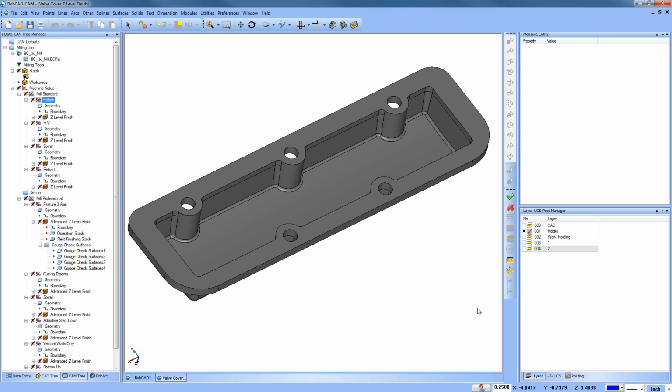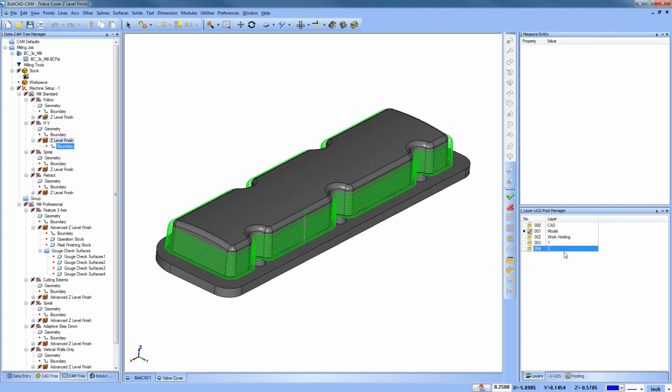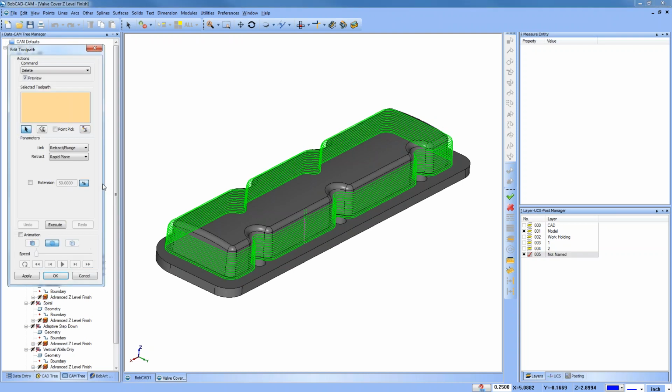Okay, there are other ways to get wireframe off an STL or a model, and one of the things you can do, and I'll just do this as a quick example, is use the Toolpath Editor. So you could apply a toolpath on that model, and then you could come in and do Edit Toolpath.